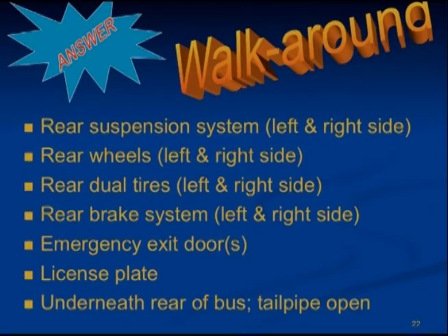Check the rear brake systems. Air hoses are pliable and not leaking, the chambers are secure, and the slack adjusters' push rod does not move more than 1 inch when pulled by hand.